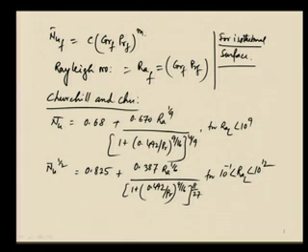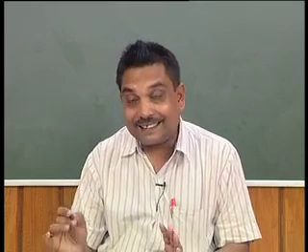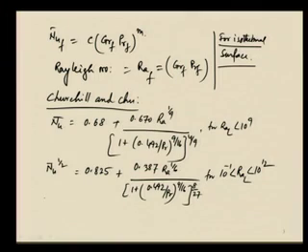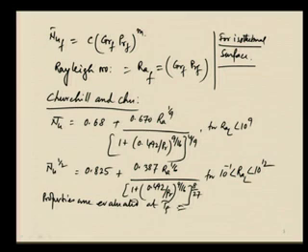So, we can find out that this second relationship is covering a wide range of Rayleigh number. I am sorry, not Reynolds number, it is the Rayleigh number. We should be very careful about that. And one thing is that the properties are evaluated at film temperature Tf, and that we know is Tw plus T infinity, the free stream or bulk temperature, divided by 2, as we have already studied several times.